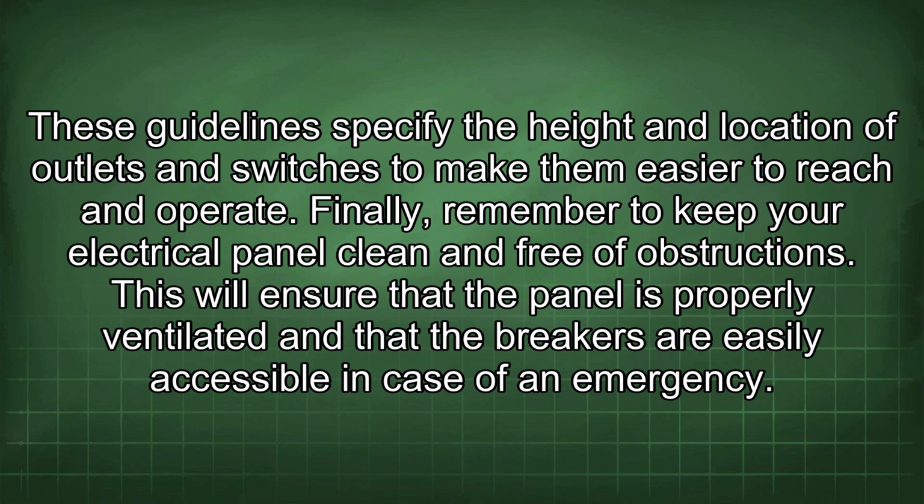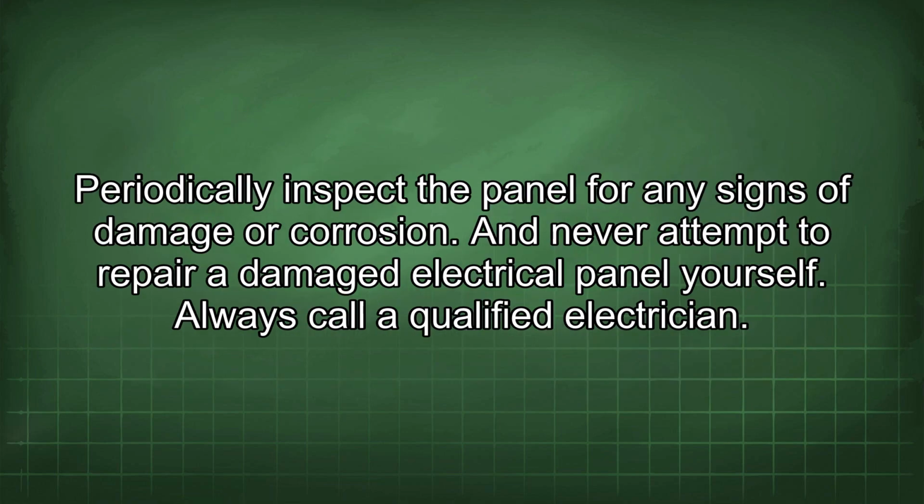Finally, remember to keep your electrical panel clean and free of obstructions. This will ensure that the panel is properly ventilated and that the breakers are easily accessible in case of an emergency. Periodically inspect the panel for any signs of damage or corrosion, and never attempt to repair a damaged electrical panel yourself. Always call a qualified electrician.